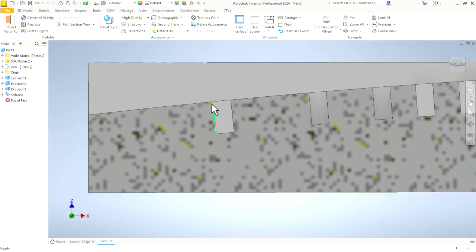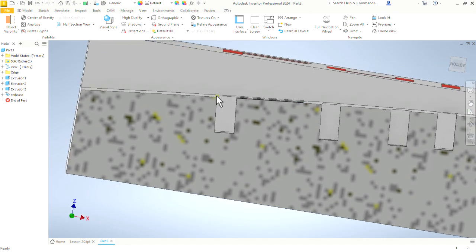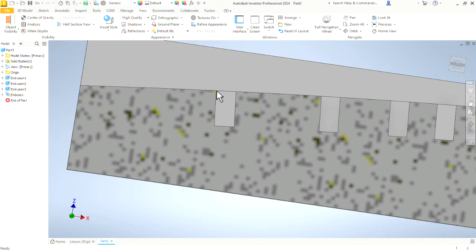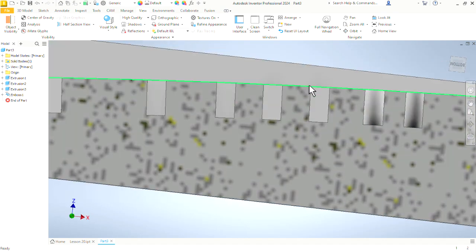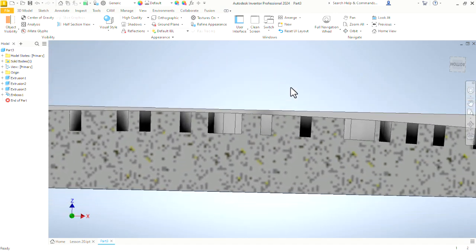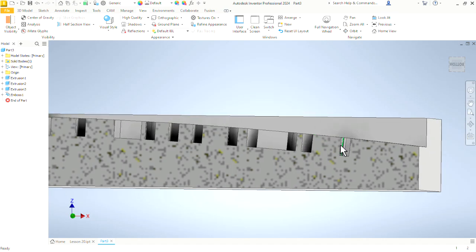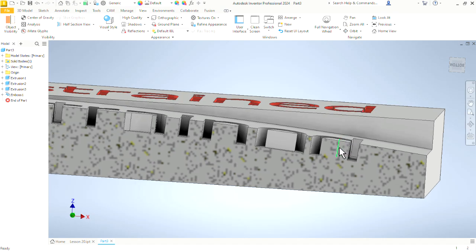So whereas previously everything went straight down, aligned with, in this case, the z-axis of the part, now we are normal to the curvature of that surface. We are coming as if we oriented the top curvature of that surface pointing straight up and coming straight down into that. And as we move across the part, everything is coming directly off of that curve. Let's go all the way to the other side, and we can see where we are tilted in, again, towards the center of that curvature.